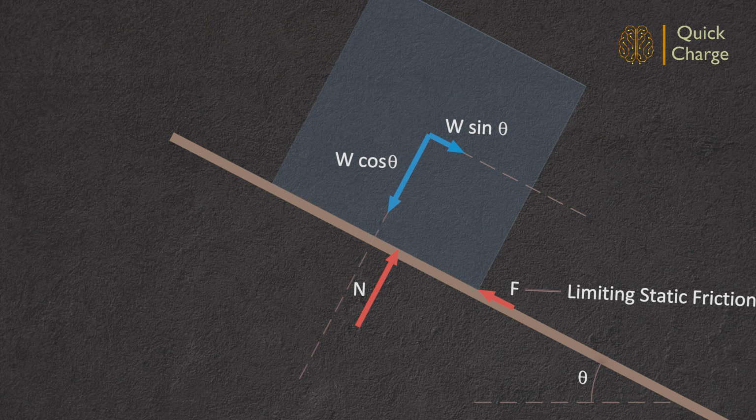As the parallel force couple increases in magnitude, the normal reaction developed will be moved further away such that moment equilibrium is maintained. The limiting angle until which a body stays on an inclined plane is called the angle of repose, phi. Any further increase in slope increases the parallel component. However, frictional resistance cannot be increased beyond the limiting static friction and motion is initiated.